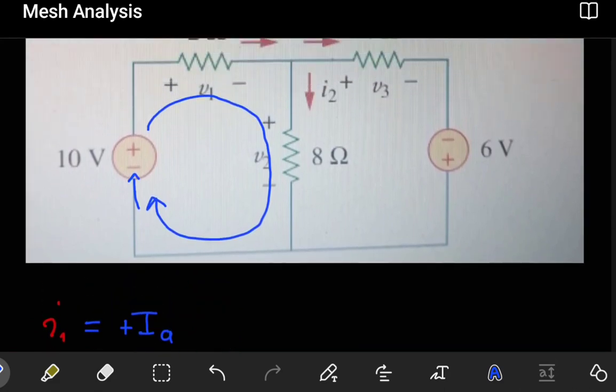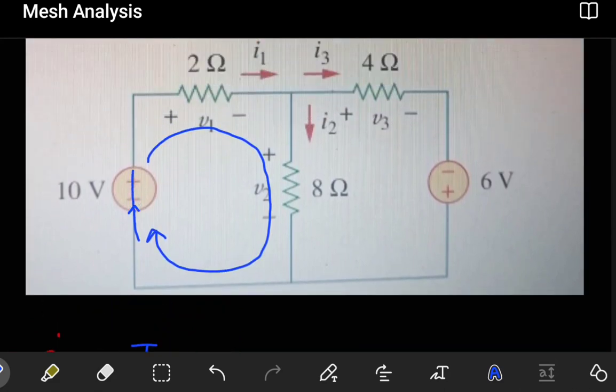So that's minus 10 volts. If we continued, we find a resistor, and this resistor is at positive 10. Again, I hope you guys have seen this in my other videos on Kirchhoff's voltage law. But if the polarity here was not assigned, it's up to you to choose the orientation. Of course, if you find your answer to be negative, it means that it's just the opposite of what your selection was. In this case, they have already been assigned to us, so we're just going to follow what